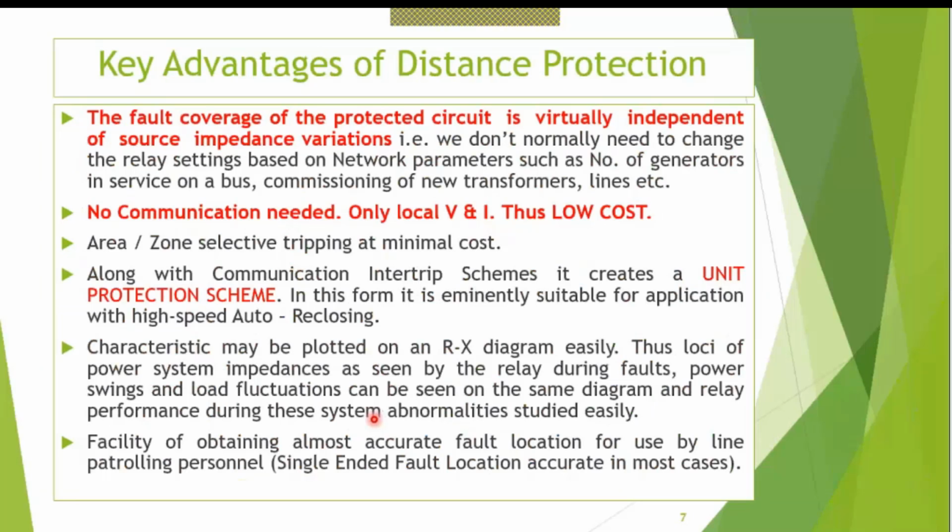Okay, now we come to the key advantages of distance protection. The first line is very important. The fault coverage of the protected circuit is virtually independent of source impedance variation. Probably this is the most important benefit that we get out of distance protection.